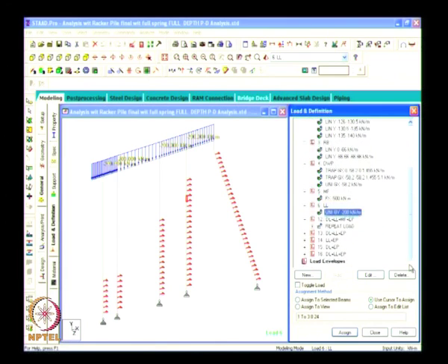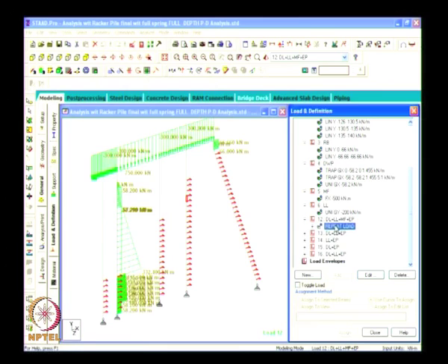So we have to do the analysis for different load combinations. Some of them will not act together. So this is one such combination. We are combining dead load, live load, mooring force, earth pressure and differential water pressure.